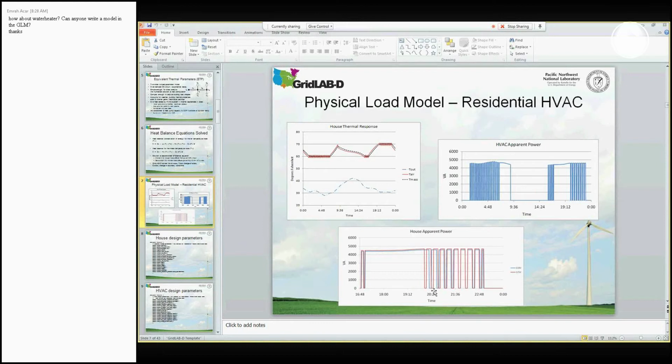So we captured the fact that, say, with a resistance heater, when you lower the voltage, you instantaneously consume less power. You can see there it's probably different by a couple hundred watts. But that means the heater ends up having to run for an extra amount of time because it still takes the exact same amount of energy to move you from, say, 71 to 70 degrees.